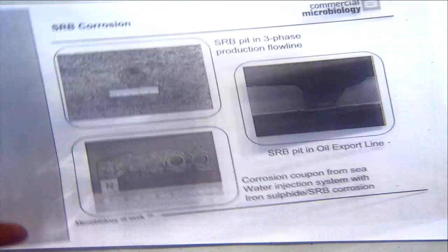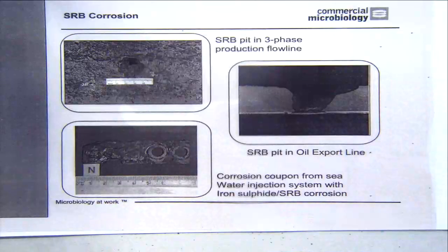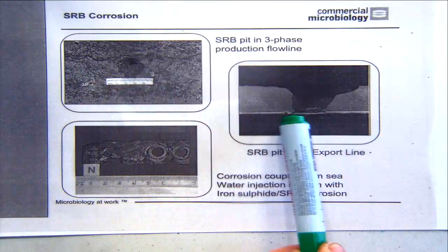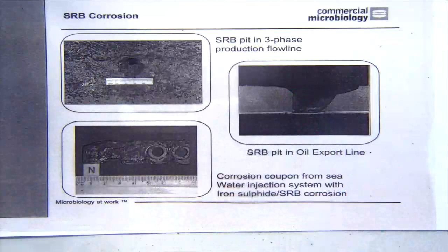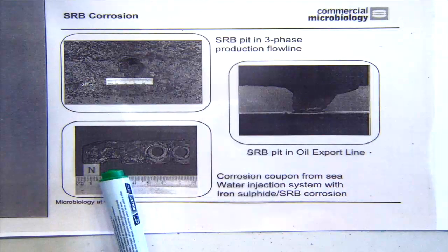On your handout you've got this diagram which illustrates a cross-section of one of these tubercles. So they're a bit like igloos, and the bacteria are living together. So it's what they call in biology a symbiotic relationship. That is to say, they join together to create this igloo, and the anaerobic ones live on the inside, the aerobic ones live on the outside.